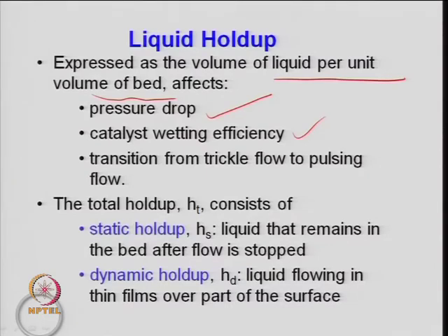So, the liquid which remains there depends on the type: that is static liquid hold up and dynamic liquid hold up. Static, as the name says, is the liquid which remains inside the bed, or is left inside the bed when the flow is stopped. This can be measured experimentally. You have the flow continuously going from top to bottom. All of a sudden you close both the valves from the top and stop the flow, and now you drain it out and check how much volume of liquid is there.